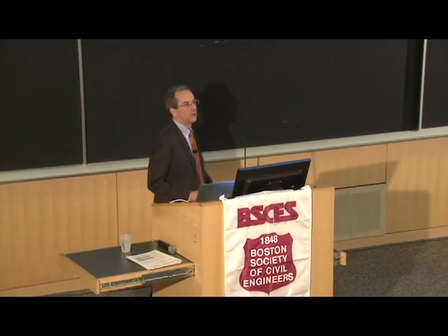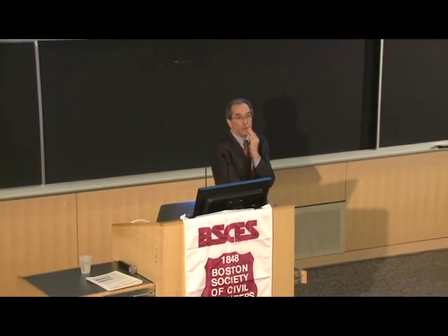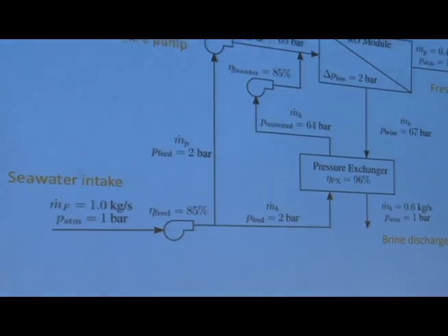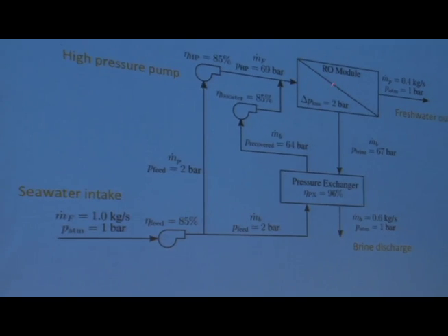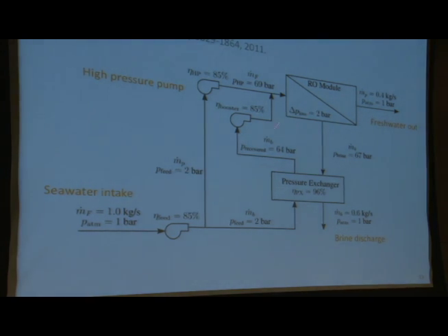So what governs the efficiency? This is a representative flow path of a reverse osmosis plant. The membranes are in this box over here, so high pressure seawater enters here, goes through the membranes and comes out as low pressure purified water. High pressure brine leaves over here. It doesn't lose a lot of pressure, maybe a couple of bar against perhaps 70 bar as it goes through the membrane. So there's a lot of energy in the brine leaving. It might be 40% of the flow.